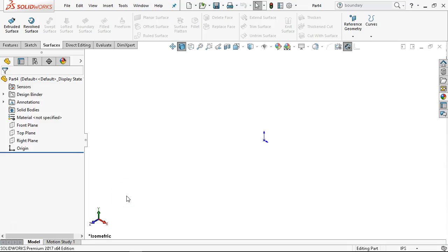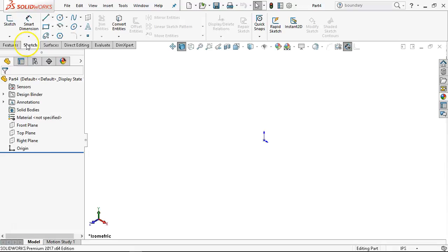Okay, so we started with a 3D sketch, and to get into some of the more complex shapes, I want to go back to the 3D sketch and see if we can extract some of that geometry. Mainly, the use of the 3D sketch is that rather than creating planes and multiple 2D sketches and multiple planes, I'm going to try and get as much geometry into the 3D sketch as I can. So I want curves in pretty much all directions, and that's going to determine whether I'm going to try and sweep with guide curves, or loft, or go back and do the boundary surface, as an example.